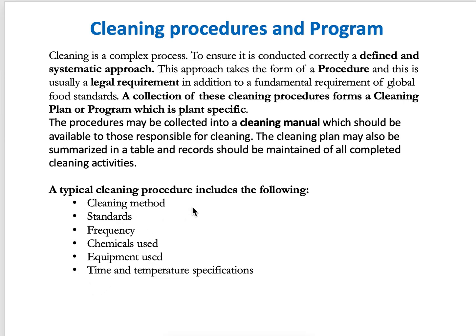That means what kind of cleaning method will be used, what is the standard, and frequency, how frequently do I have to do it. Do you have to do it every day, or every hour, or every 6 hours, every 2 days, something like that. Also what kind of chemicals will be used, what equipment will be used for the cleaning, and for how long the cleaning procedure should be run. Do you have to clean for, for example, 30 minutes or 1 hour or 10 minutes, and at what temperature. Do you need to do the cleaning at warm temperature. Everything should be in the procedure.